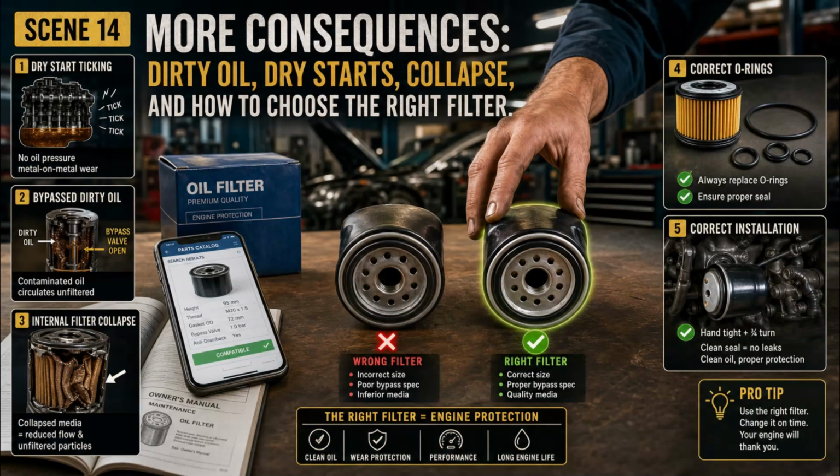So the answer is simple: oil filters are not universal, because the filter that almost fits can still leak, bypass, drain back, or restrict oil in ways your engine was never designed for. Use the filter specified for your exact engine.